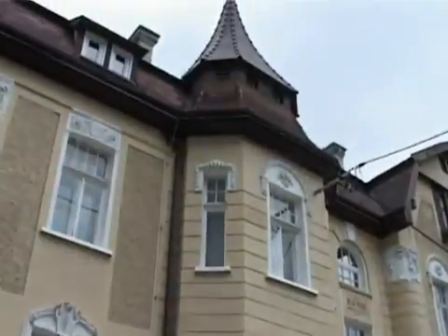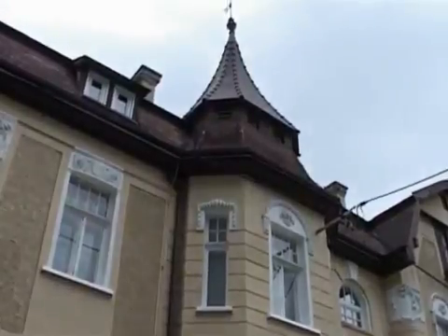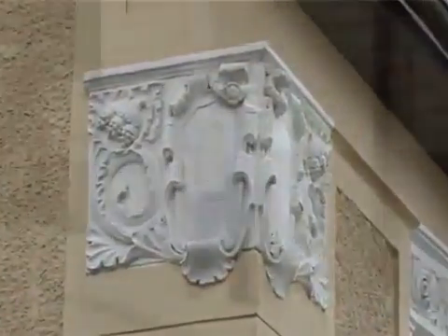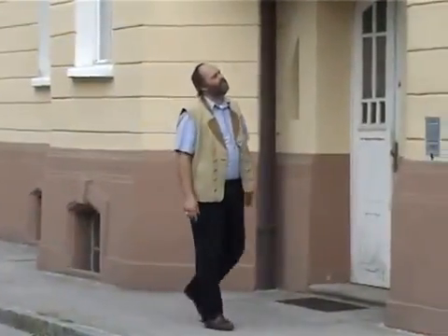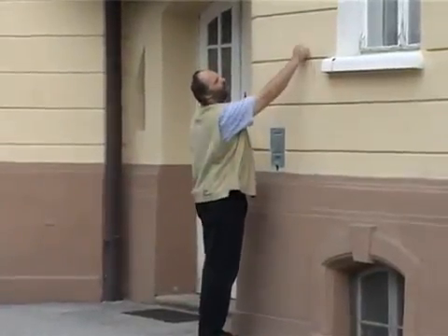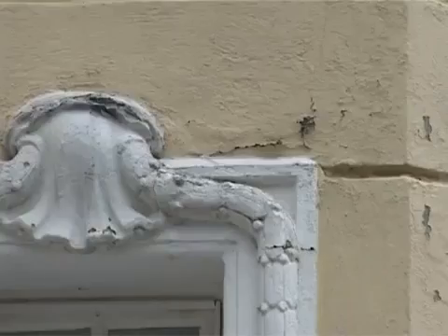Thanks to these very good properties, the open-pored and water-repellent renovation plaster does not permit any masonry moisture to pass in liquid form, but only in the form of vapour, which is humidity. Hence the plaster looks dry from the outside for a long time. But appearances are deceptive. The wall behind remains wet.